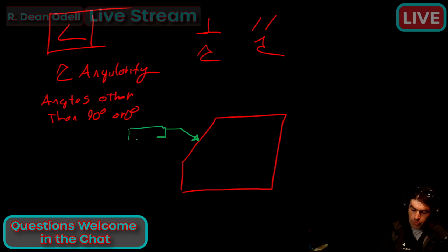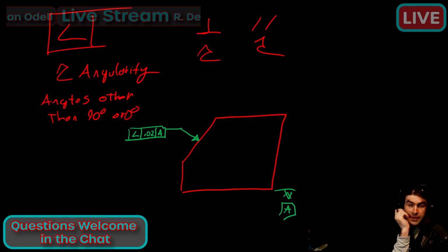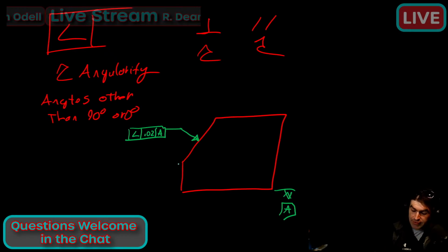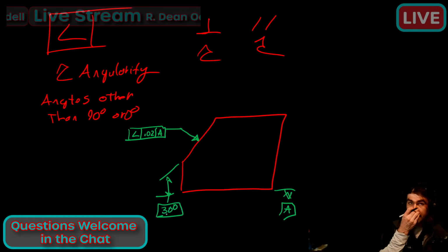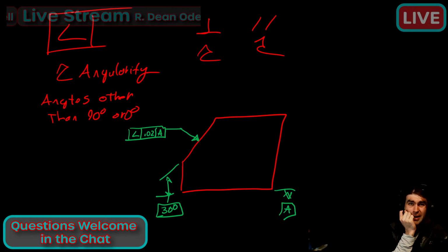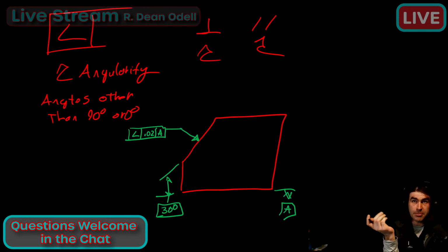We can control this surface with angularity to a datum reference frame. Now, with angularity, probably the biggest thing is that we have to specify the angle. I know it's a terrible job of showing an angle, but essentially we have to specify that. Well, it brings us to the question of, wait, where do the basic angles for everything else come from?